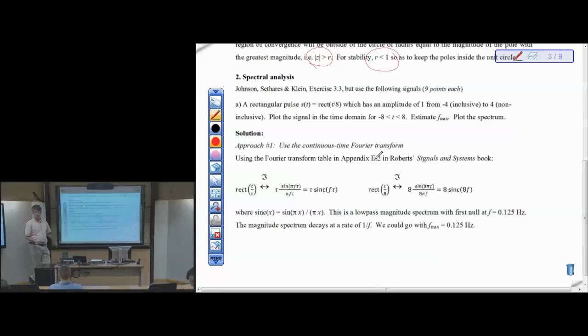bandwidth of any signal. You measure something in the lab, you don't usually have the formula for that signal over all time. You have data. You've captured measurements. So we want to find a way to capture measurements and figure out what the effective bandwidth is, or equivalent bandwidth. So for the first part of problem 2, you know the continuous time Fourier transform exactly. You know the null-to-null bandwidth exactly. Then you can compare a simulation approach to finding that effective bandwidth, because you know what the answer is. So you know the ground truth.